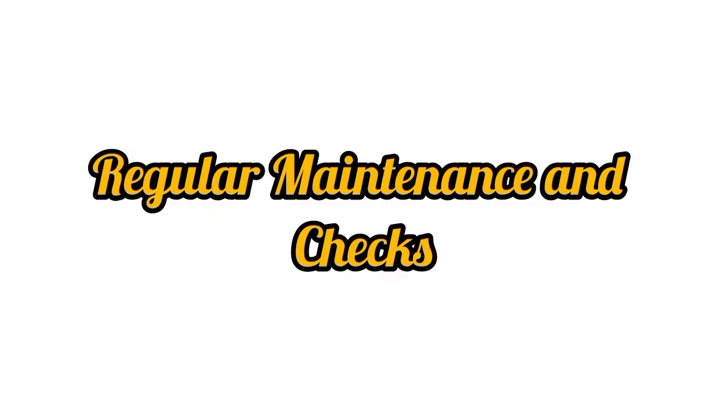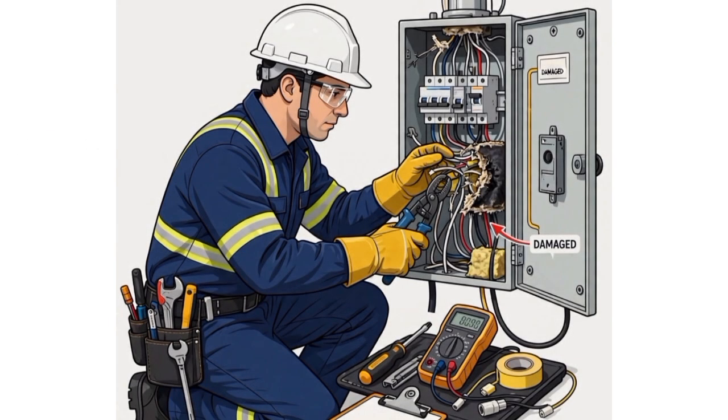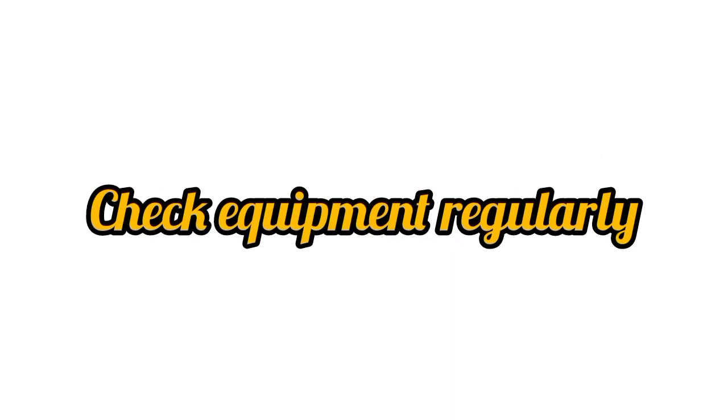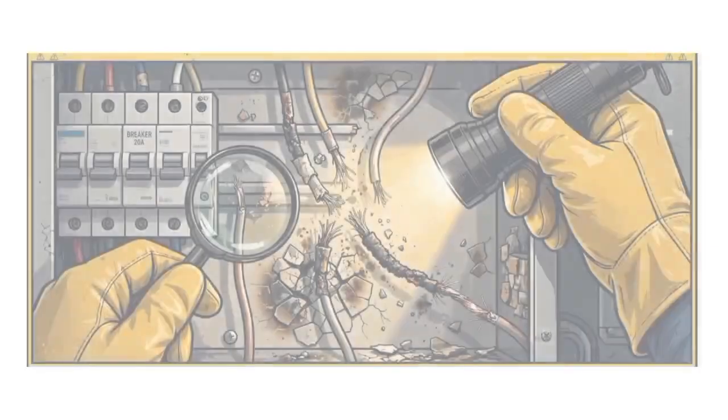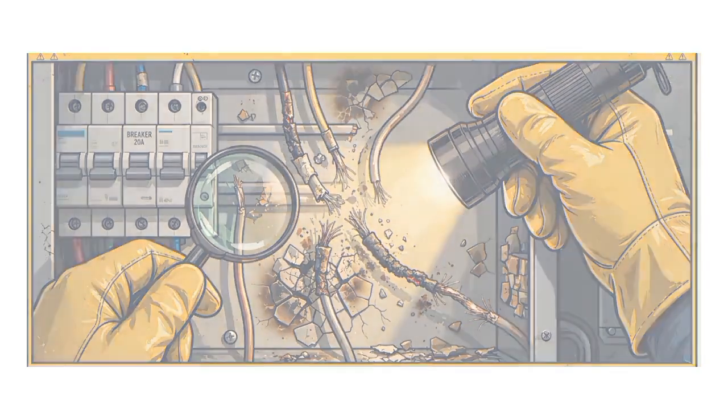Regular maintenance and checks. Electrical equipment can wear out over time. If wires, insulation, or connections become damaged, they can cause dangerous electrical arcs. To prevent this, check equipment regularly. Inspect electrical systems for any signs of wear and tear, such as frayed wires or cracks in insulation. These could lead to an arc.